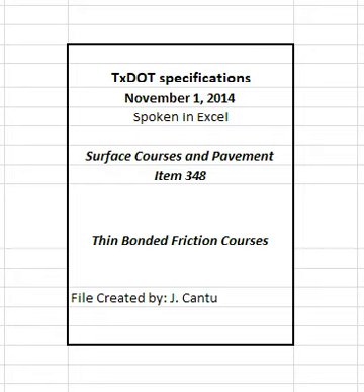4.7.3.1.2 Thermal imaging system. Review the output results when a thermal imaging system is used, and provide the automated report described in Tex 244F to the engineer daily unless otherwise directed. Modify the paving process as necessary to eliminate any recurring, moderate or severe, thermal segregation identified by the thermal imaging system.